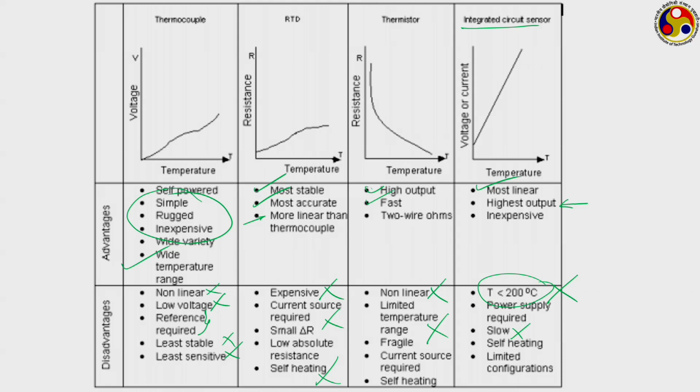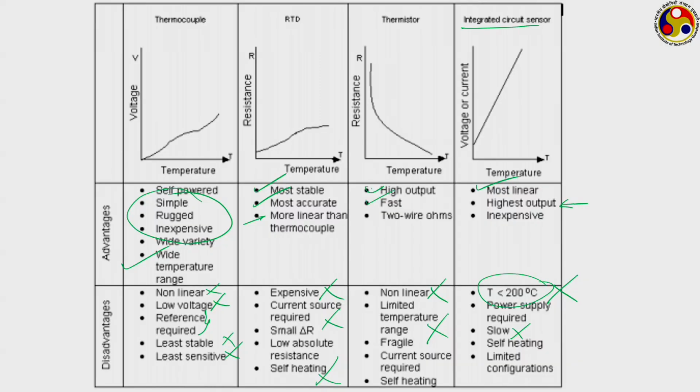So if you are looking for applications which are quite rough and you have a large temperature span and you want to measure temperature at several points, thermocouples are ideal compared to RTDs. And if we specifically need a very linear output at low cost, then IC based sensor or bulk junction semiconductor sensors probably are the better option. So with this we move on to the next category, where we shall be talking about the use of emitted radiation from bodies for temperature measurement.